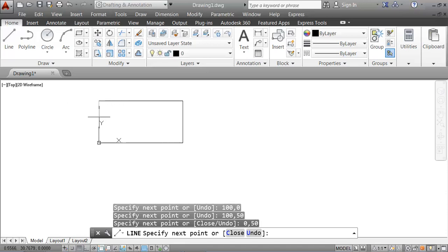You're going to remain on 0. It means you say 0, comma, how much do you want to go down? 50 millimeter. Where you are, you are 50 millimeter high. You say 50 minus 50 is equal to 0. Then you type 0. When you get it, just press enter to finish, and the exercise is done.